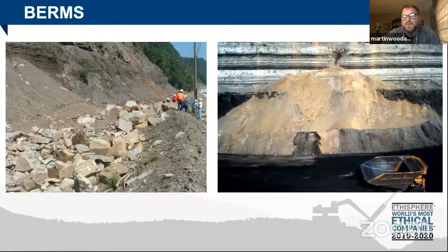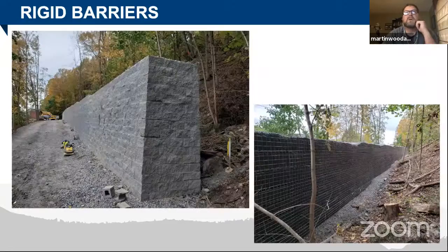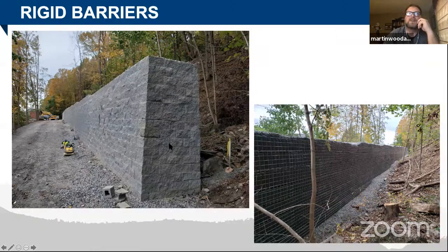You can take the next step, which is to take the berm idea and squeeze it. We have been using what are called geosynthetically confined soils, or GCS walls. These are kind of like the berm, but we've put walls onto the sides to be able to catch rockfalls. This is in the state of New York, where there is rockfall coming down. There's a road just about 15 feet to our left, and we needed to catch rocks that were about 15 to 20 feet in diameter. Sometimes these are the measures you need to absorb those kinds of forces: a rigid type of barrier that goes in there. I don't think we've ever been able to fail one of these with a rockfall. They can absorb a lot of energy. Sometimes they have a little deformation and they're easy to fix, but these are that next step up.